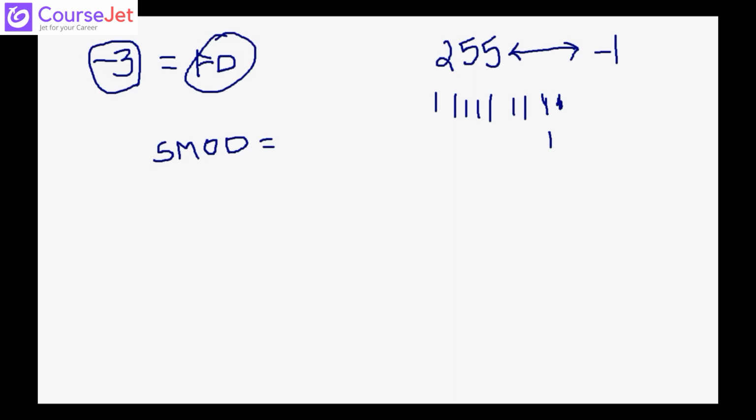In that, the first bit is this SMOD bit, only one bit. If you make this bit 1, it doubles the speed. If you have selected 9600, the speed will become 19,200.